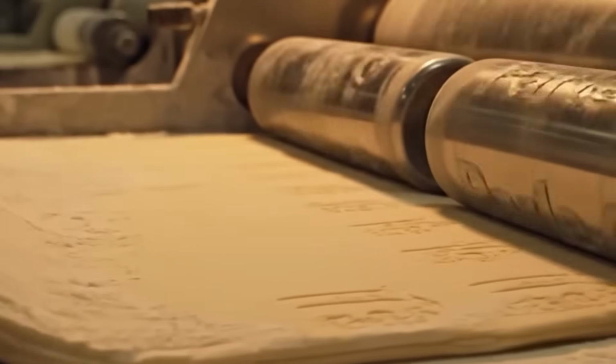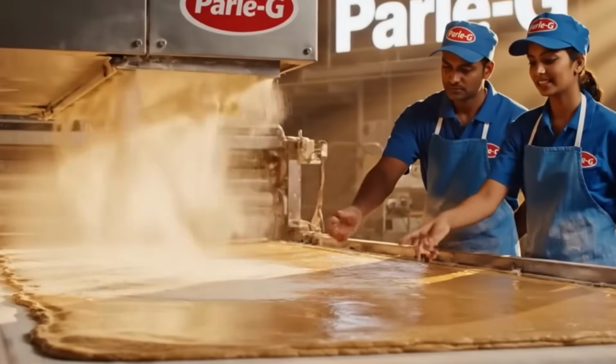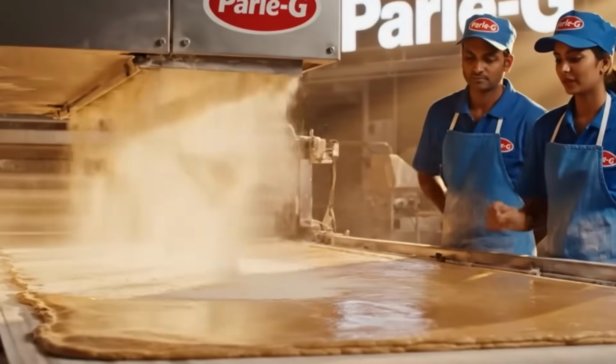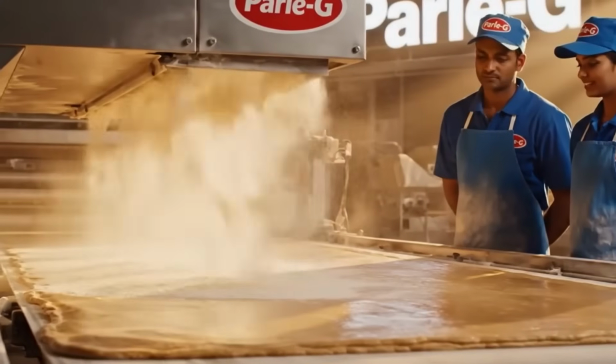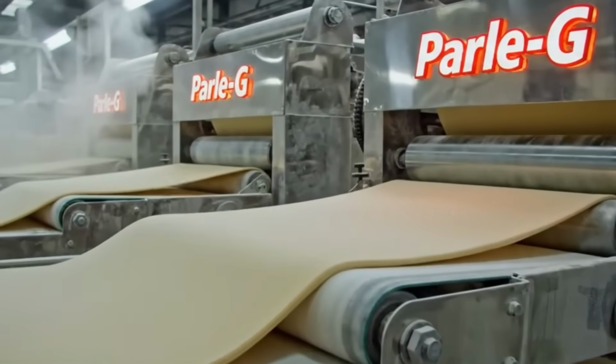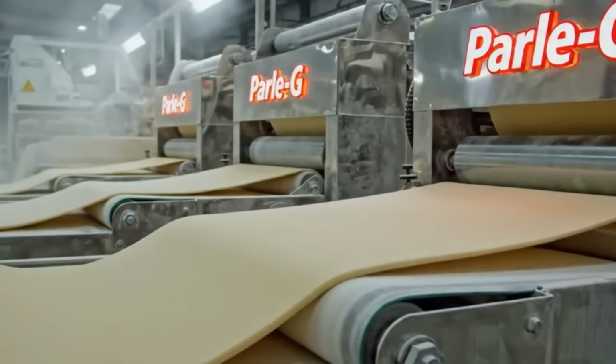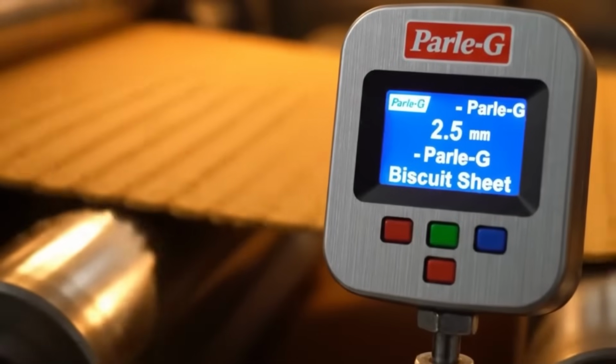Baking is the main transformation stage. Biscuits enter a tunnel oven with multiple heat zones. Early zones apply heat that sets surface structure. Fat melts and the dough begins to relax. Water begins to evaporate and steam forms within the piece. Leavening reacts and produces gas that creates internal porosity.